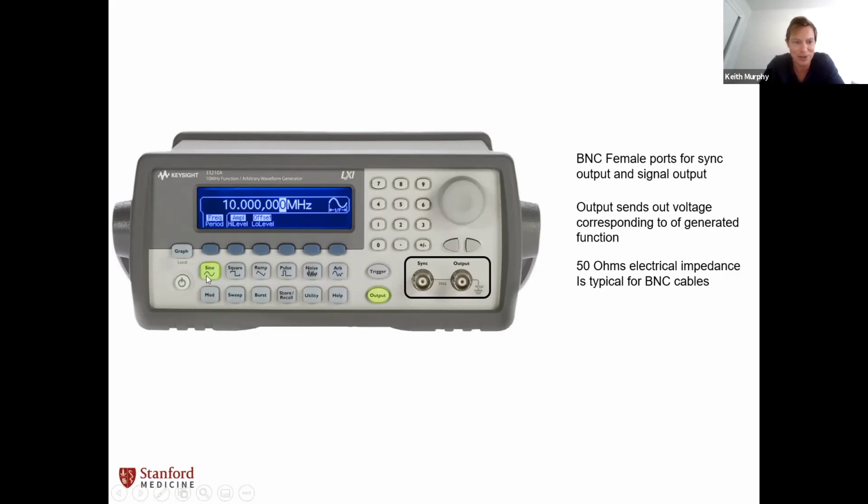And I think we skipped past this, but any function you have here has a number of different properties. Kim mentioned one is the fundamental or carrier frequency. Here it's 10 megahertz, you can see. It also will ask you for the amplitude. That's how much voltage you're kicking out, whether peak to peak or from the zero state to the peak.